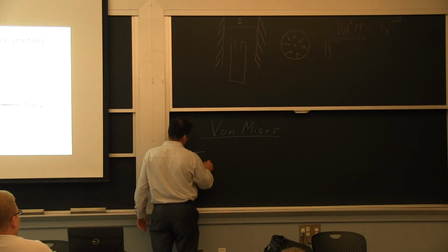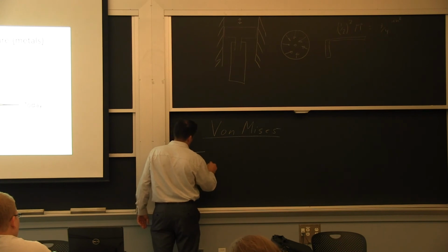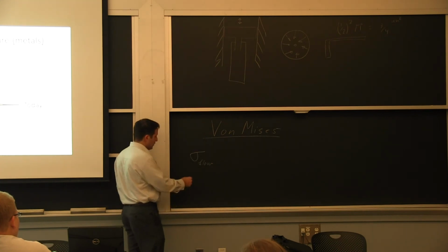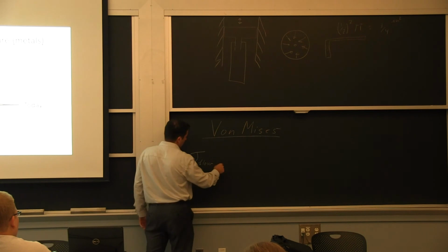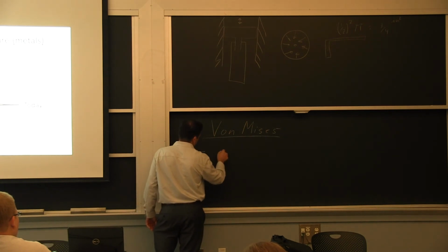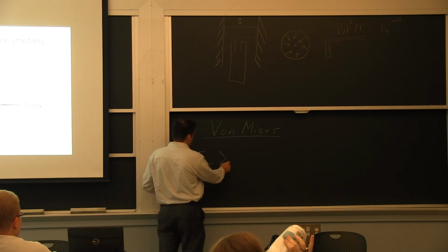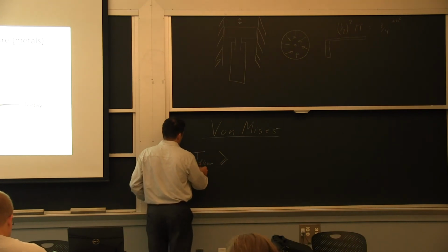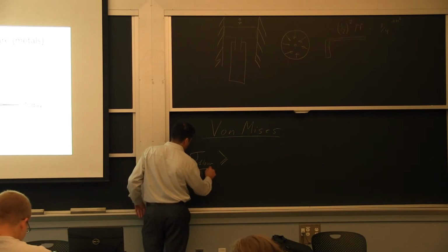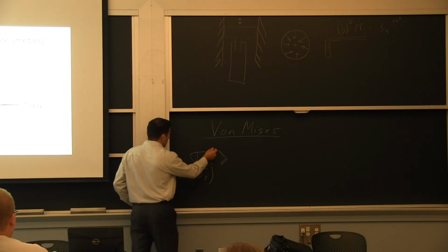At any point in time, you have the flow stress. If you're talking about a material in service, normally you use the yield here. So the criterion is it's going to flow if the stress exceeds the capacity of the material to resist flow. So I'll put in parentheses here, sigma yield. It's a material property.